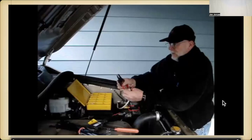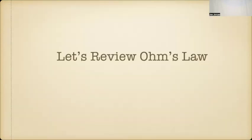And never just solder a wire that you're using for a battery cable or something number 10 and up. Because if you just solder it, it comes loose and the terminal gets hot, the solder just melts and the wire falls out of the connection. It's not a pretty thing. Anyway, a fair amount of experience in that.